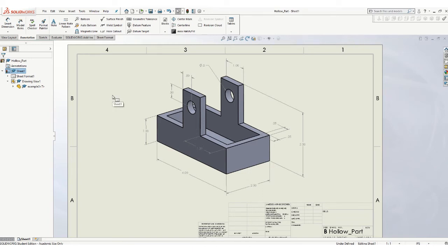In this video, I'll show you how to make a hollow part like this. There's multiple ways to make a 3D model. In this case, you could build each of these individual sides and the bottom, or you can do one sketch of the outer dimensions and then hollow it out. I'll show you how to do that.